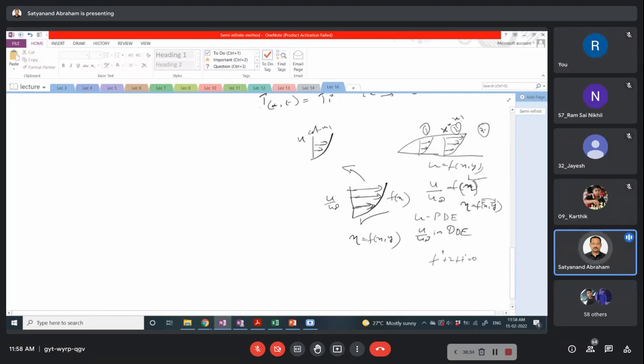If you want the velocity profile at x equal to x2, from here you will get a profile that is a bit different from that at x1. So this is u at x2. You are getting a single profile. That means this profile u by u infinity is the same everywhere, because x and y are combined into a single variable. There is no variation of x and y separately. If you vary eta, it inherently varies x as well as y.